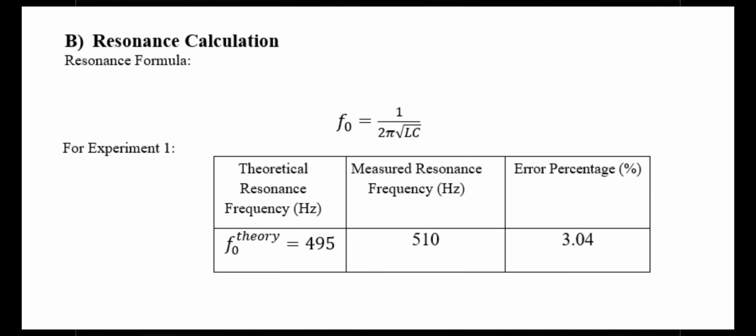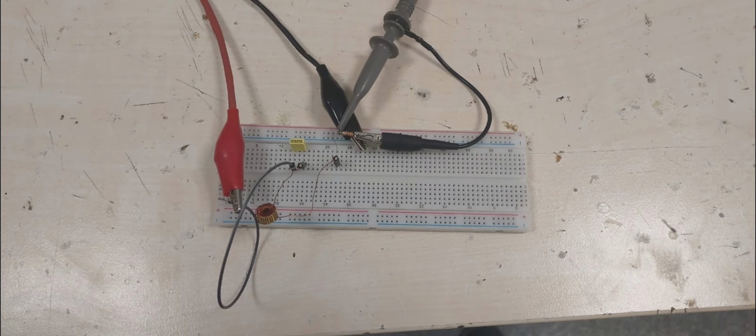But I had a small deviation from the theoretical results. The resistor, inductor and capacitor don't have exactly their labeled values, so the resonance frequency is slightly different from the ideal one, with a 3% error rate. The inductor and cables also add some extra resistance. Also, I measured the frequency in steps instead of continuously, so I might have skipped the exact points of maximum current. All of these effects can cause small differences between theoretical and measured curves.